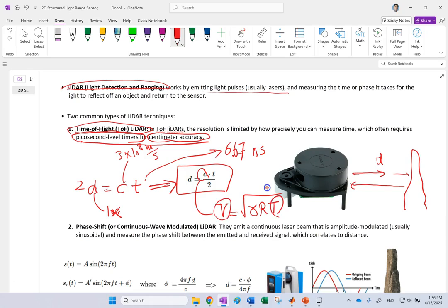So if you are using an acoustic sensor outside, where the temperature is not under control, then depending on the temperature, the speed of sound might not be exactly what you always think, 342 meters per second or something. It could be smaller or bigger, where T is, of course, in kelvins.